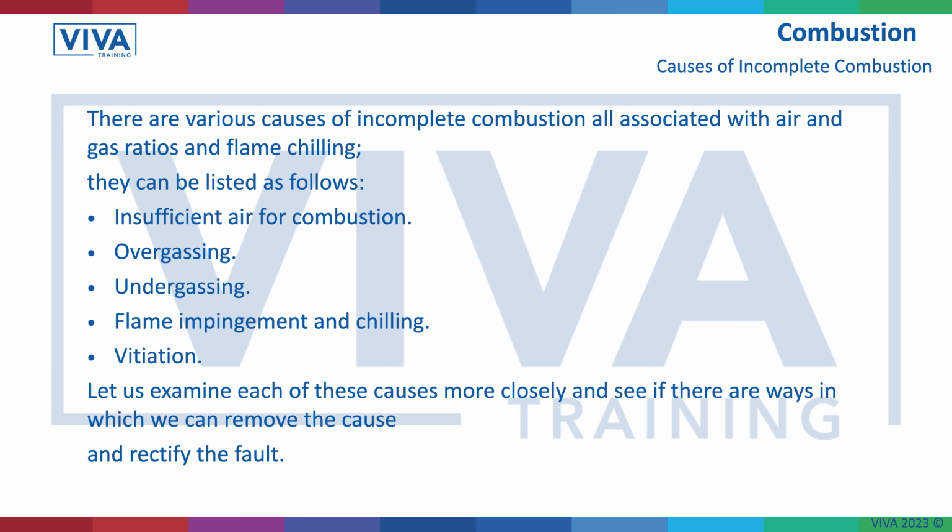So there's a lot of reasons where we get incomplete combustion. So we're going to look at some of those. Insufficient air, we're not getting enough air in. Now that might be we haven't got enough ventilation coming into the house. The customer's blocked up air vents because of drafts and things like that. It could be the appliance hasn't been serviced for a while, so it's got blocked up with fluff and dust into the appliance itself. It could be we're putting too much gas into the appliance. It's not being set up correctly. It might be we're not putting enough gas into it. So we've got too little gas, which is affecting that combustion process.